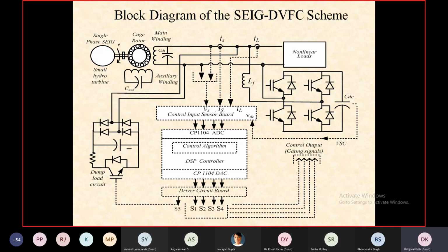So at that time in the laboratory, the high frequency diodes were not available. So I used the power frequency diodes. But that power frequency diode will not work at high frequency. Therefore, in that case, I had to have a DC filter capacitor. That is why I connected it here.